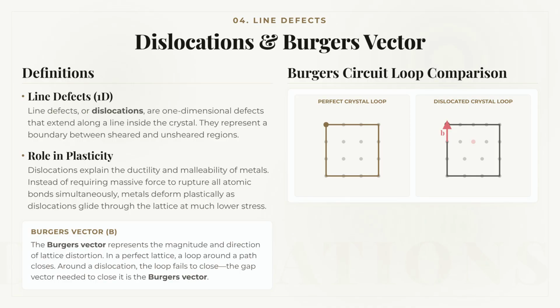If crystals were perfectly ordered, they would require extremely high forces for deformation. However, real crystals contain dislocations, and these dislocations can move under applied stress.